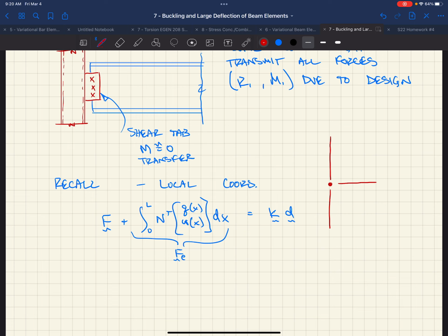This column's extending in and out of the page vertically. If we had a shear tab, right? We know that that member is not going to provide any moment transfer from the forces that are acting on it into that column. And so VA denotes it by this little circle, and I'll show you guys that, so you know what's released and what's not released, okay?